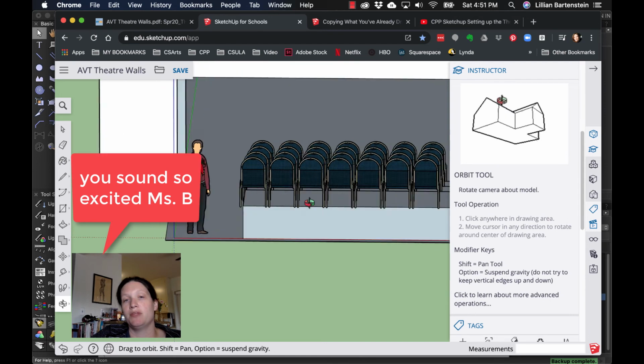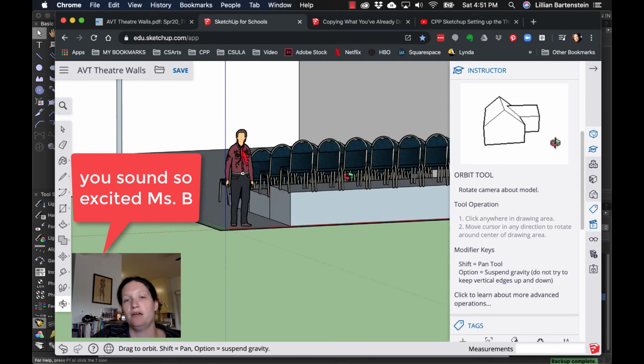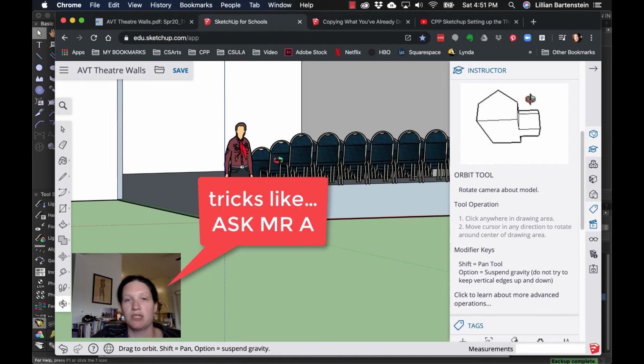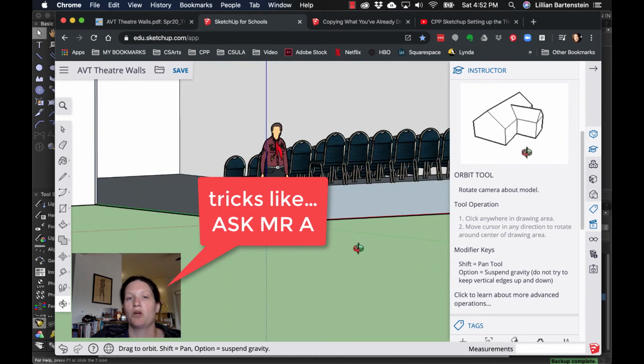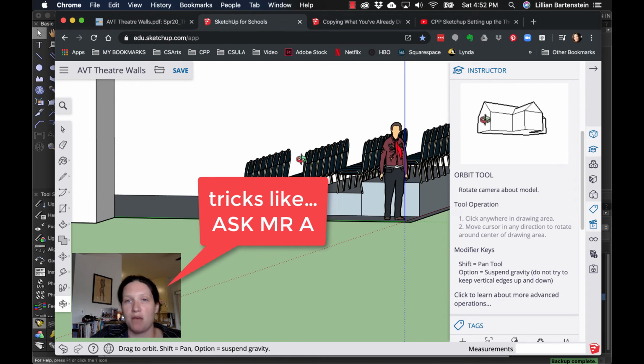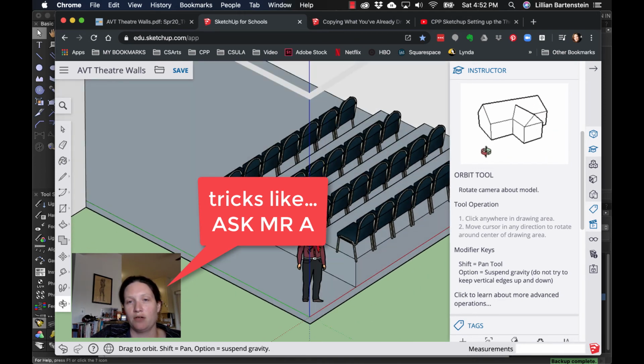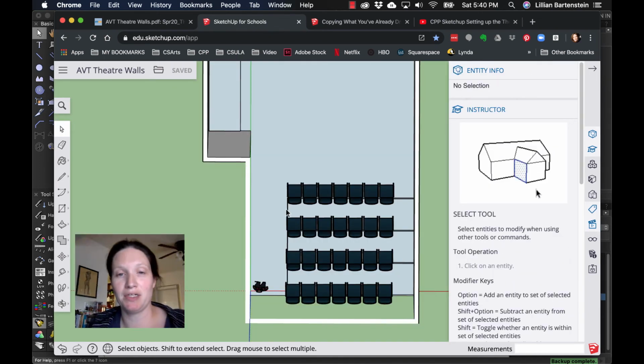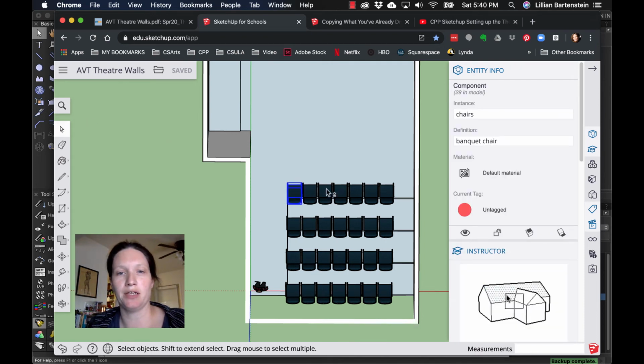If you have trouble with this, it's okay. You can use all of your same tricks that we used in Vectorworks. So if you need to select a group of chairs, work on them from the side to raise them up, that's a good approach, etc. Okay? So I would then go back to my top view. I would come in here with my selection tool, right? There it is. Hold down Shift, select this whole group of chairs.